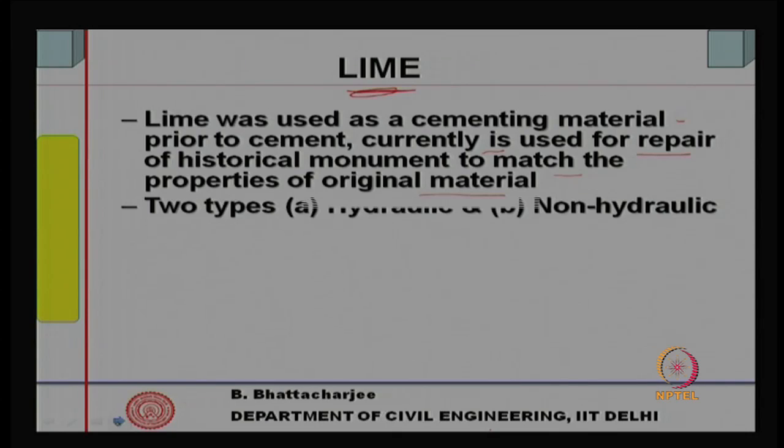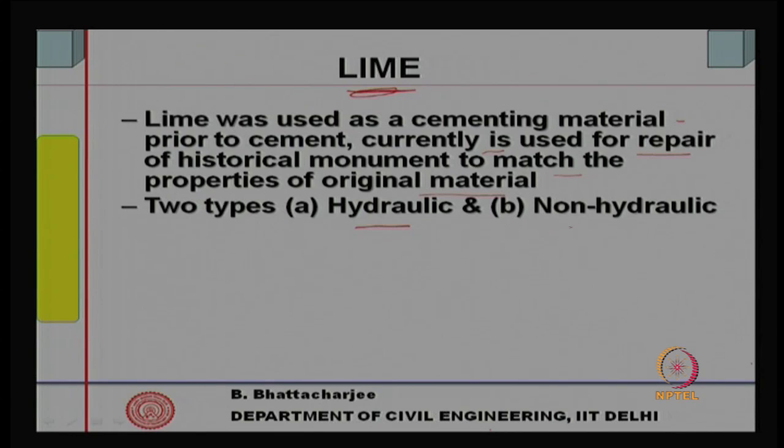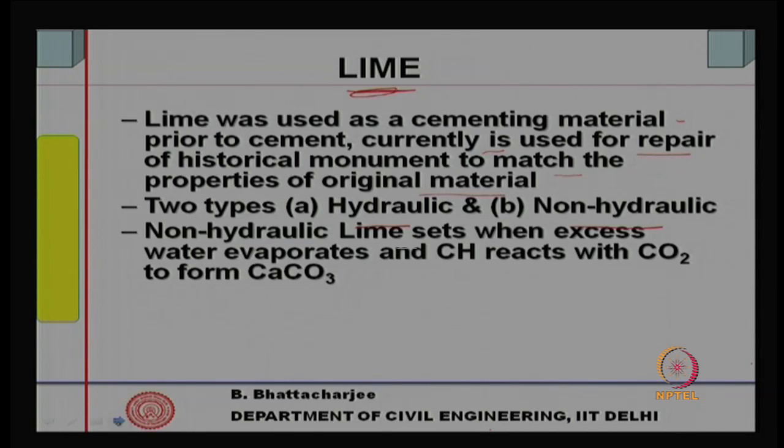Now, in India, of course, we have used lime together with what is called surki, which is nothing but the dust that remains below the brick kiln when you burn the clay. So, it is burnt clay, some form of fine powdered burnt clay, we will come to that. Now, lime itself is of two types, hydraulic and non-hydraulic lime.